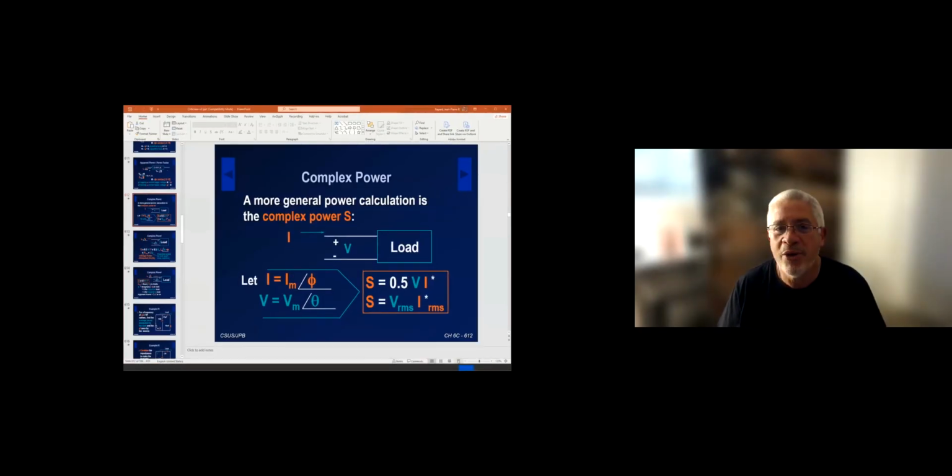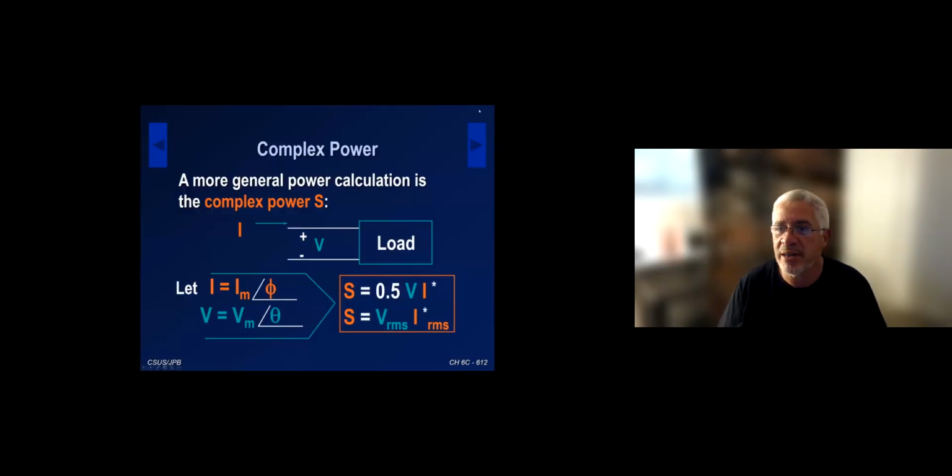Anytime we discuss power, we are talking about a circuit that has been solved, using nodal, mesh, or other methods that we've seen in the past. So we start this discussion of power by looking at a particular passive circuit or element. The reason I know it's passive is because my current is entering the positive terminal. If it was a source, the current would be entering the negative terminal of the voltage.